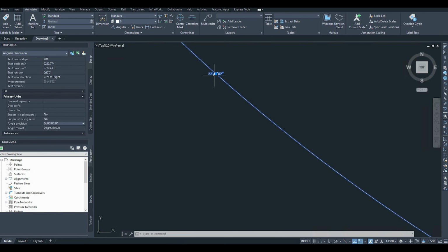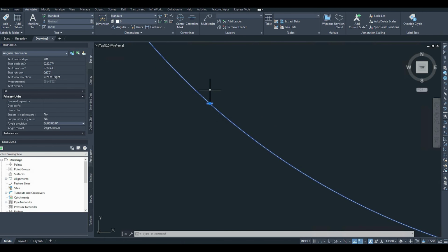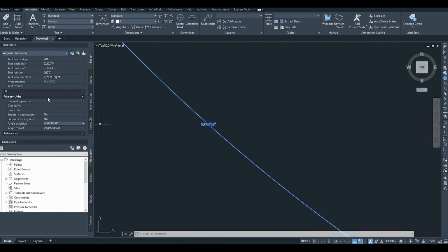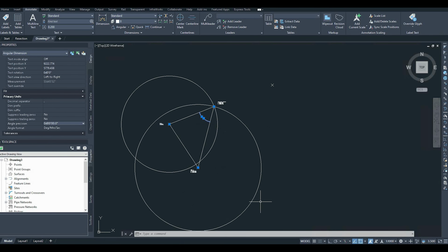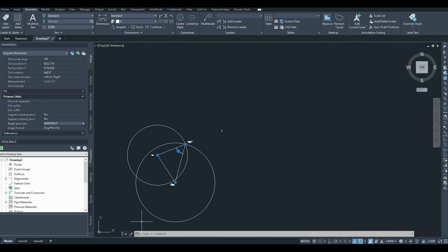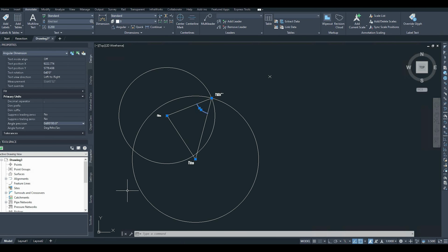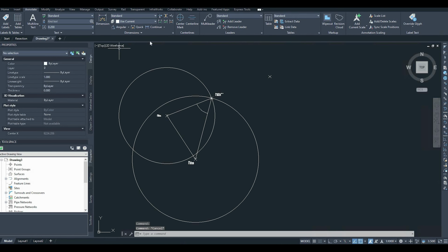Okay, let's return here. And of course here, guys, you can use your skills that you learned in AutoCAD and Civil 3D to make this text larger from the properties here. I'm not going to go through this in more details, but you need to improve now the presentation of your work as well. And then if you like to prepare it to be printed to a scale, you can do the following. Okay, now we completed the resection, guys. And then, as I mentioned, from annotate, you can add the dimensions, you can do the measurements of the lines and the angle, etc. To present this in a better way, you can change the size of these descriptive texts here around.